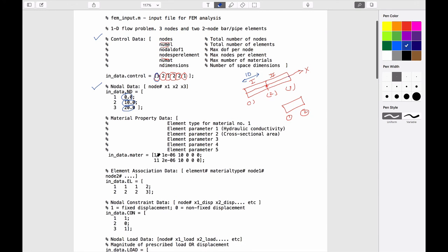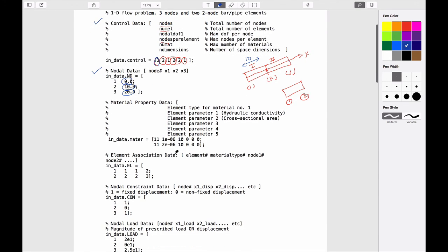So the next piece of information is the material property data. We have 2 materials, which is this one here. So we have to have 2 material property data cards. That's a hark back to when information was put into a computer on cards. So we're going to need 2 of these cards, and we can define in this element subroutine.